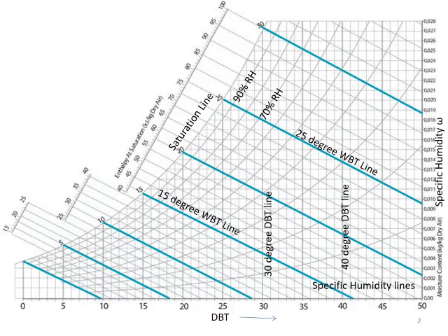Now next is wet bulb temperature lines. All those blue colored inclined lines are the wet bulb temperature lines. Then how to read this wet bulb temperature? On the saturation line of this psychrometric chart, you can see there are markings 5, 10, 15, 20, 25, 30. These are the temperatures corresponding to WBT. Here if you come down from that saturation line, the 5 or 10 at the bottom also coincides with the DBT. Means actually it can be read from the DBT axis itself.